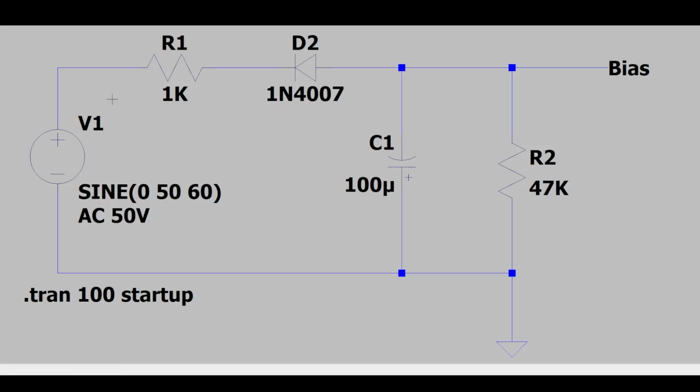I will, before applying the voltage doubler, get everything else fixed on the Hiwatt. We will then measure the bias, see where it sits. I will then show you how I'm going to implement the voltage doubler circuit into the Hiwatt amp. And then we will again measure the range of bias values that are available.